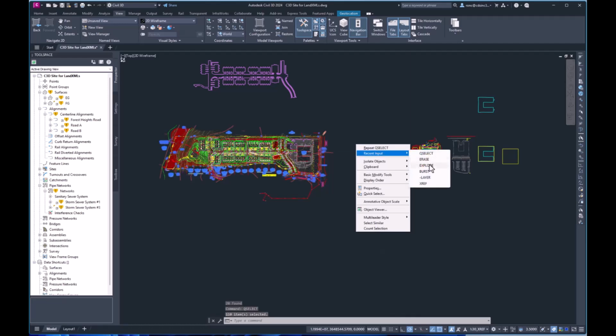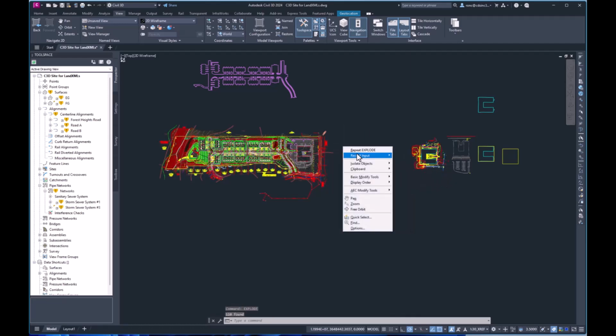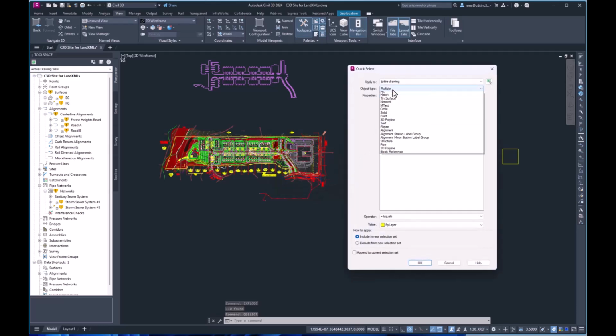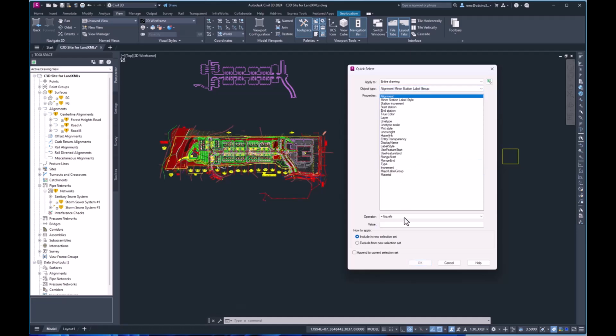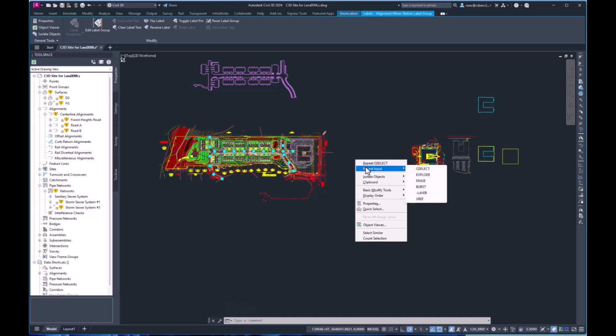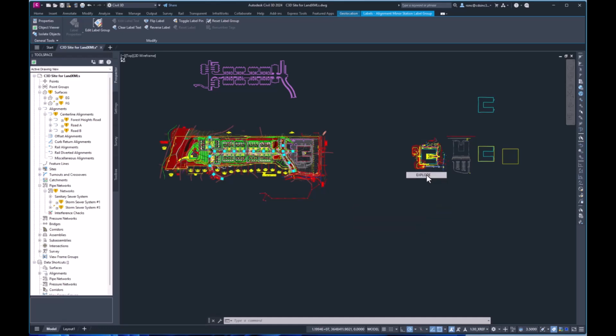I explode this. And this is just a process that we do with every job, every CAD file, dumbing it down to basic elements. Okay, pipe, structure, we're not going to do that yet. Now, they have stationing for the alignment plotted somewhere. If I say OK, you can see it's along the alignment. I'm going to explode this.